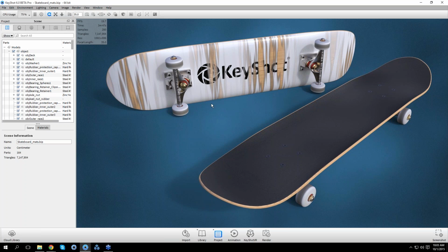And then I'll set up this scene here pretty much from scratch. I'll have some basic materials applied, but show how the procedural textures were all applied here. And some of this stuff can only be done in KeyShot 6 using the material graph. So I'll try and kind of save that stuff till the end and keep it more general for the first half.